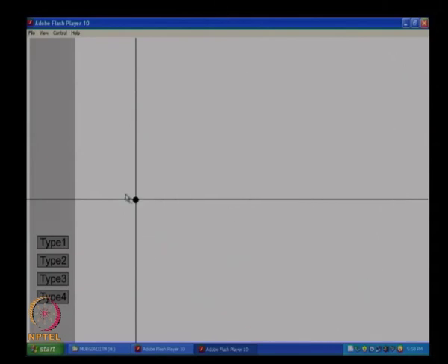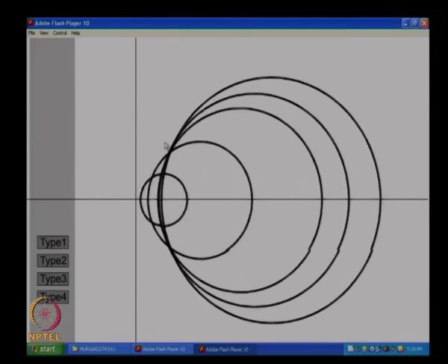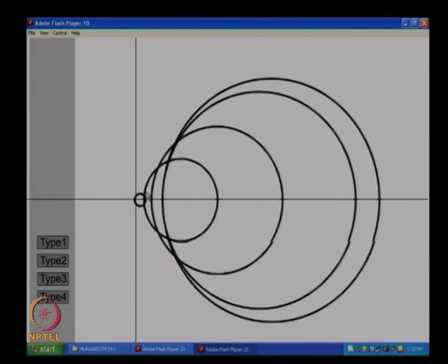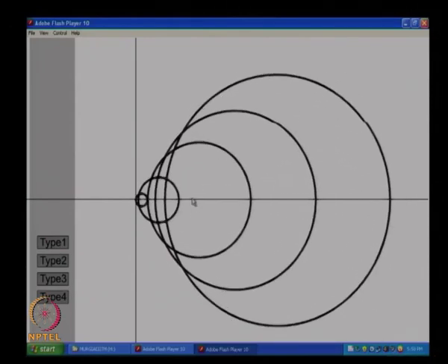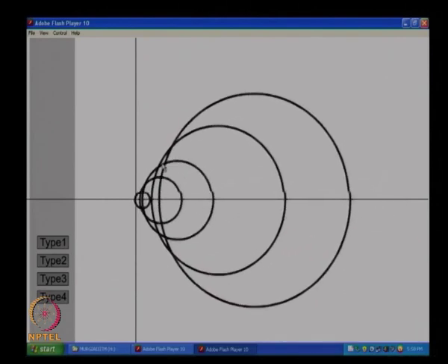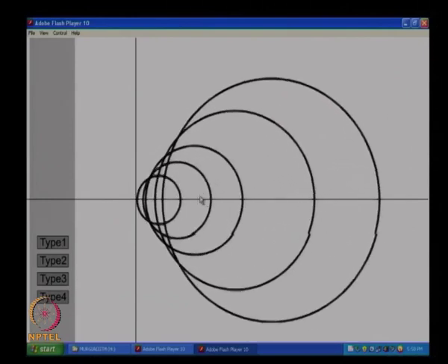That is what we see, and this is how you create your supersonic flow Mach angle. If I draw a line along the tangent of all these circles, the angle I get across here happens to be your Mach angle. This is the simple illustration of this.